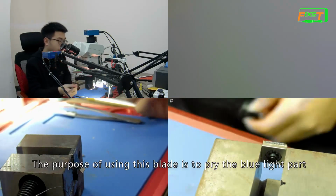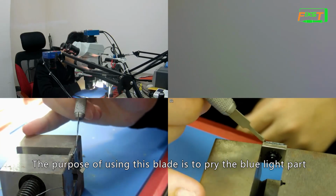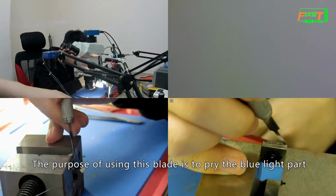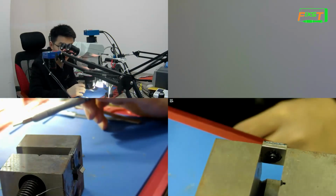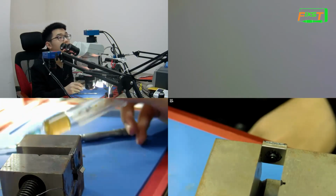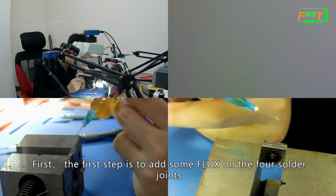The purpose of using this blade is to pry the blue light part. First, the first step is to add some flux on the 4 solder joints.